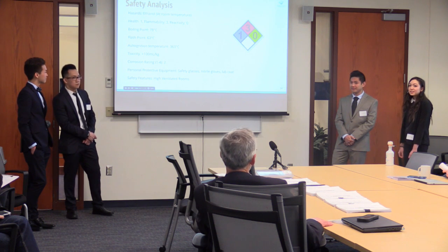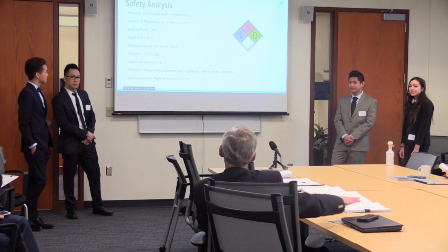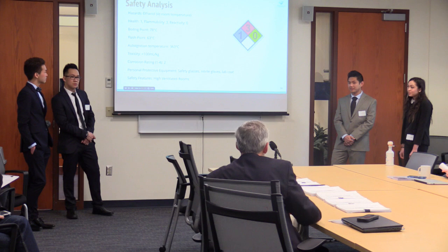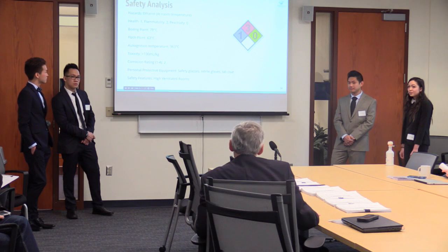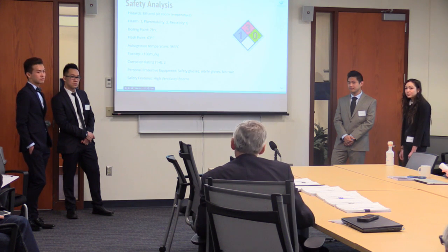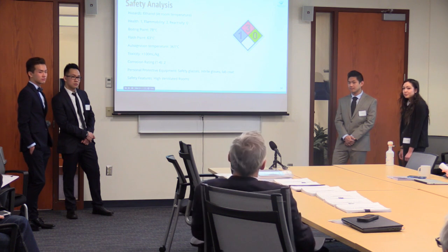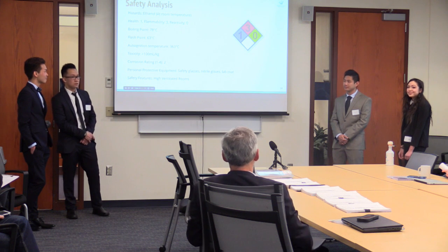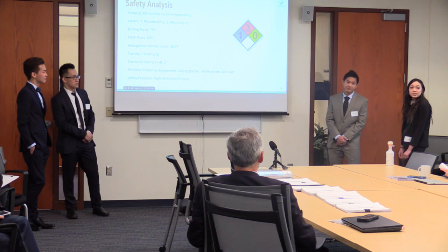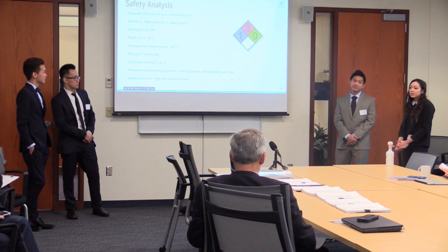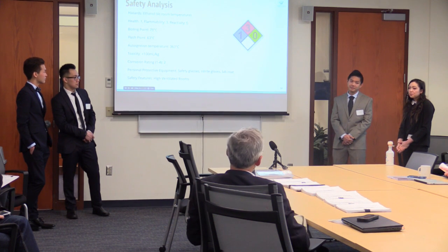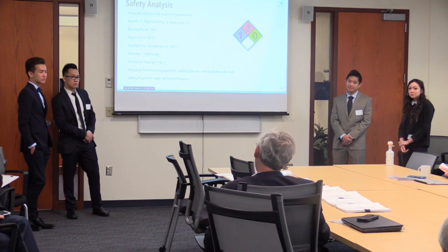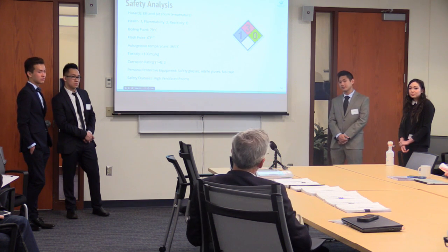And I tell you that from experience in biotechnology, everybody uses 20% ethanol to wash down surfaces, and you have to be very careful with it because 20% won't pass the fire code in most municipalities. But you've got 70% and you're aerosolizing. Worst of both. So what do you think you could do if you find out there's a problem with the concentration of ethanol that you want to use? Even the ethanol spray coming out of the can could generate a static charge and cause a spark, and that's enough to ignite it.